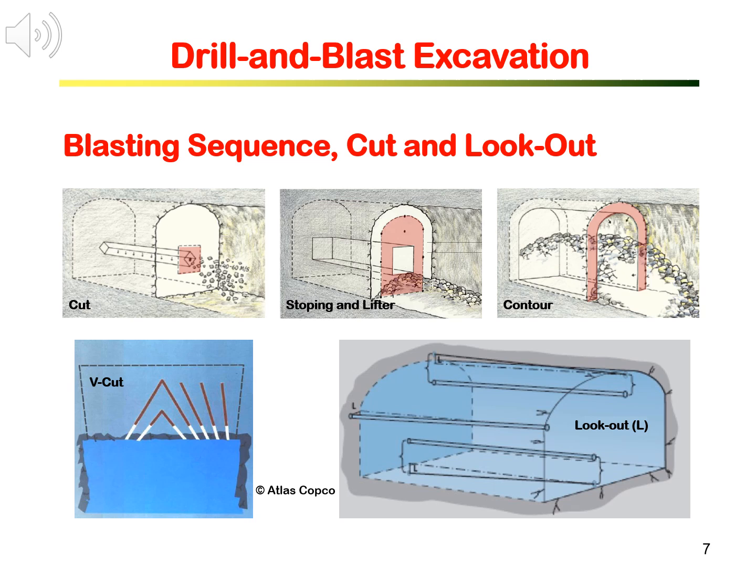Blast is done in sequence, with time delay in blasting. It starts with cut blasting, usually around the center of the excavation phase. Then it is the stoping blasting, forming the main excavation. The final blasting is a contour to produce the final surface of the tunnel. There are several types of cut. The common one is the V cut shown below.